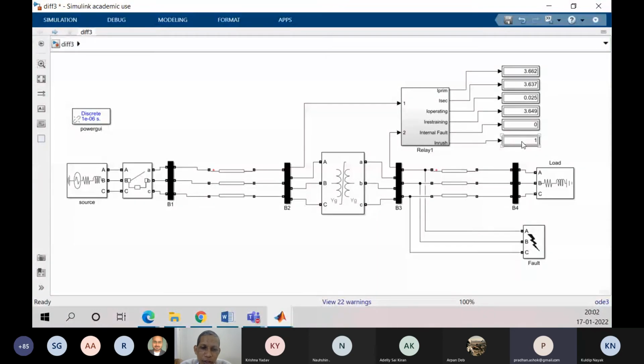So this inrush current, the relay may not consider calculating here. It may calculate, but that cannot be considered in the decision process because it has not gone to consider differential current. It is below the trip characteristic, because both the restraining current and the differential current are at par. So there is no need to consider the inrush. If that point goes beyond the curve, then only you consider the inrush situation. So this last I, the one here, becomes redundant, not required. So these are the things to be there.